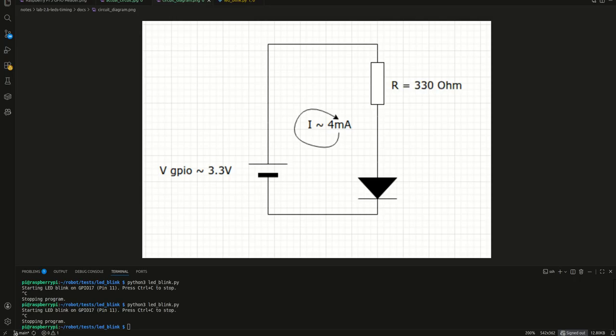The resistor protects both the LED and the transistor driving the pin. With proper sizing, current remains predictable and safe. If components are not sized properly, failures become dangerous. A damaged LED can behave like a short circuit. Without a resistor, this can effectively connect the output directly to ground.